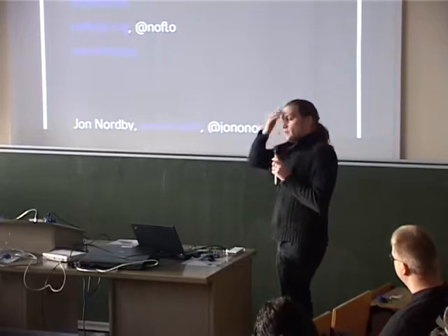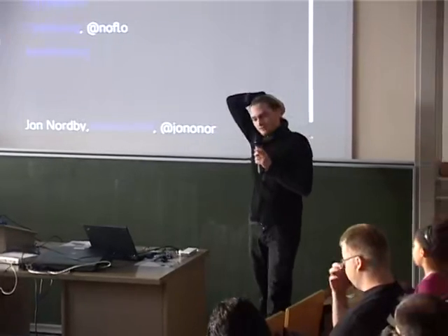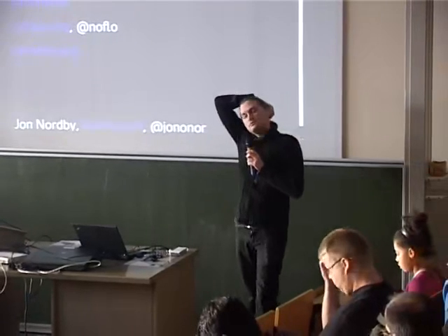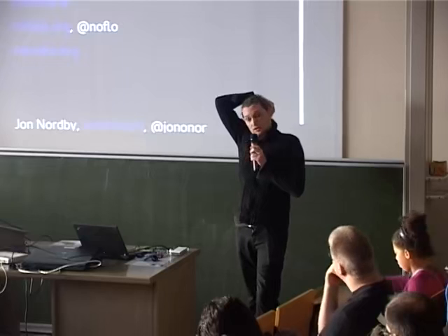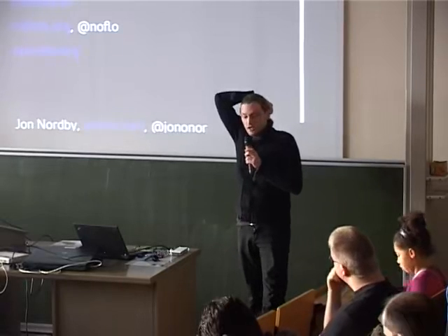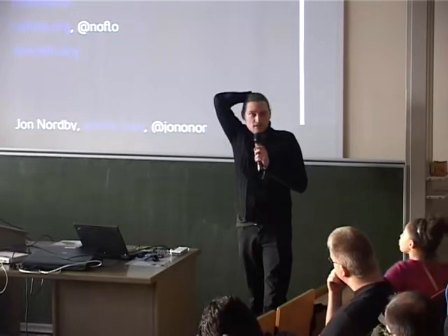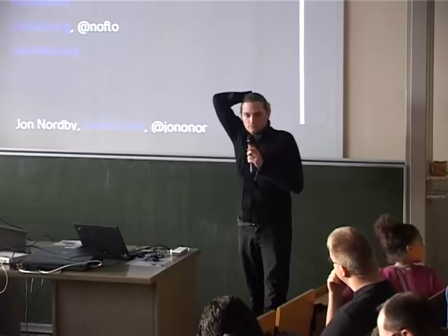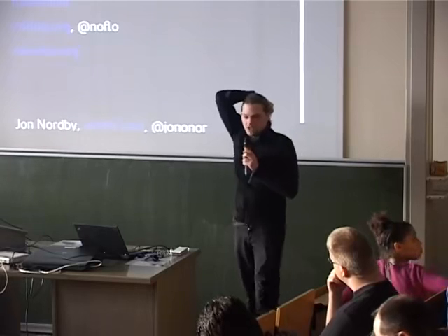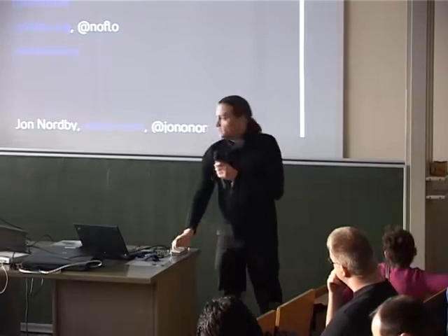It's running with 500 bytes of SRAM and something like 16K of program memory for the standard image. It can run on an ATtiny, which has a total of 700 bytes of SRAM or something like that. So it's pretty low. Questions?